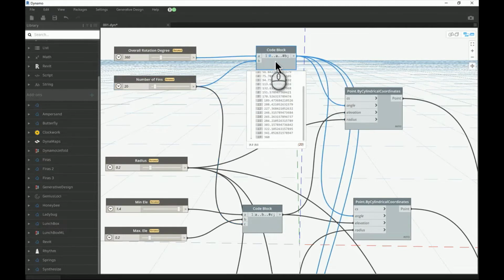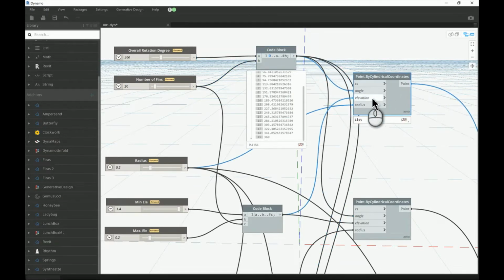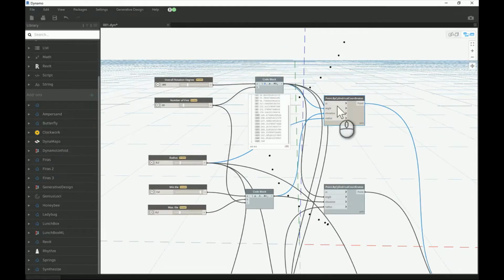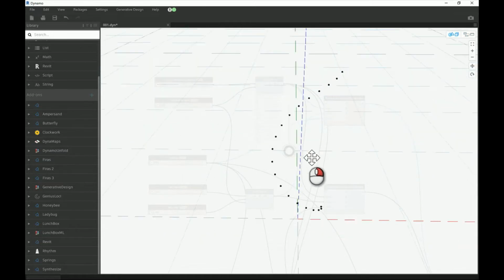This is a range. That's the start, which is 0. That's the end value fed by you here, and those are the number of jumps specified by the value of B. All of those are given to the angle. So we specify how many elements will be located at each angle. I will open that to preview, which might help you digest this first piece of information. And we probably need to zoom out also, so you can see the spiral generated.